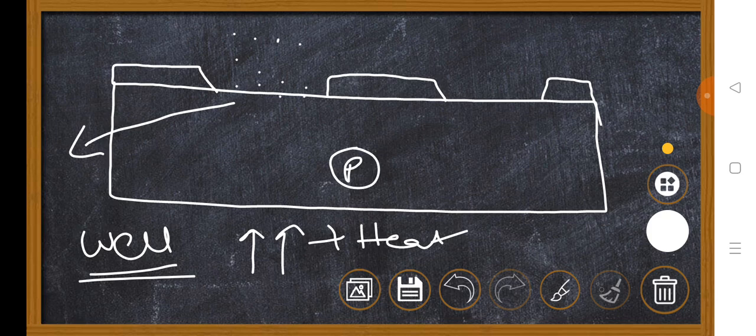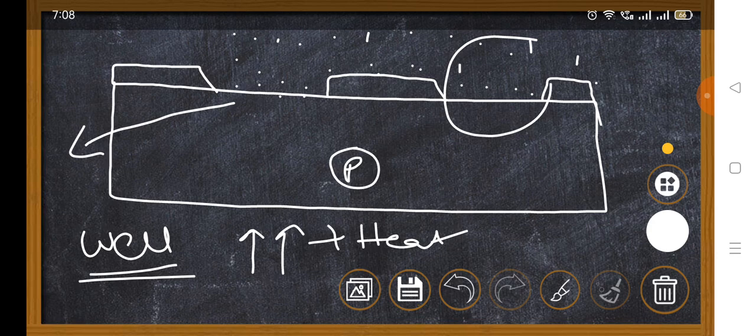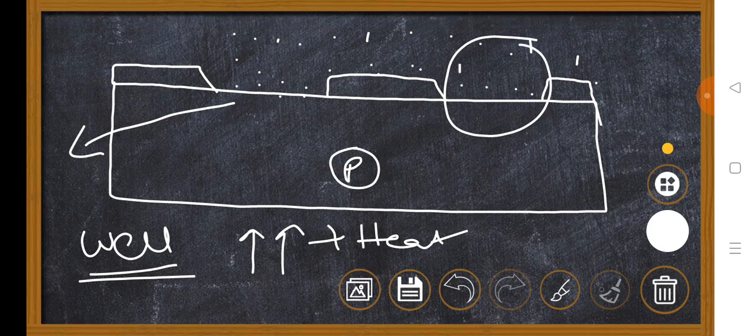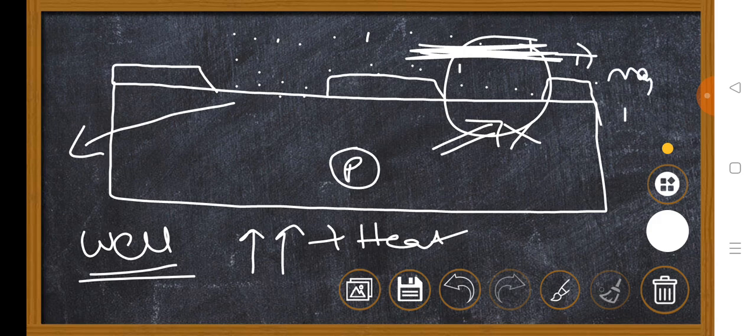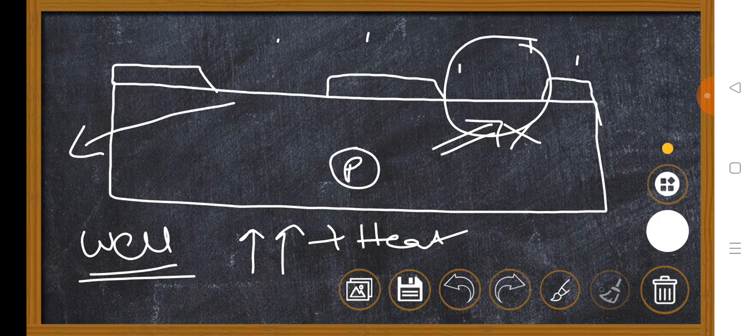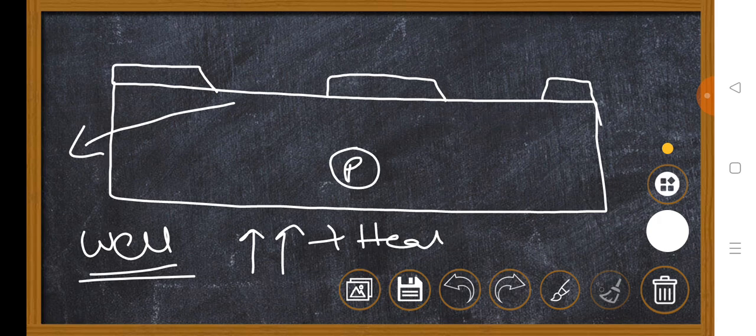Don't forget, when you are exposing n-type impurities gas onto the substrate, definitely here also there is a window open, therefore here also there is a chance of forming a well. But here we don't require any well, therefore you should cover here with a mask. I hope you are clear. You should cover with a mask. Is it clear? Therefore I'm going to perform, observe very carefully.